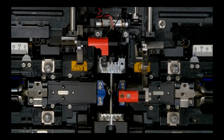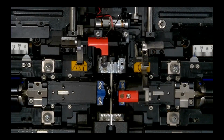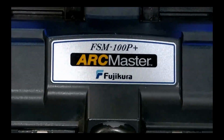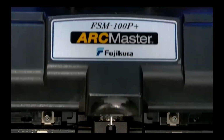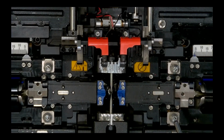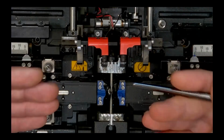Now, an important thing to note here is while you can do this, the wind protector is not going to close in this configuration. If I put both of my clamps down and try to close the wind protector, it's not going to close. The splicer will act like it's trying to close, but it still won't close because the wind protector is physically being blocked from closing. So in order to close it, I'll have to open these. However, they are independently operable and they are motorized. So when the splicer closes the lid, these clamps will physically move down to apply clamping pressure onto the fiber.